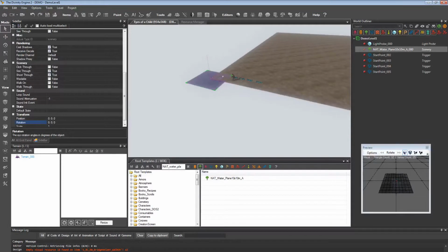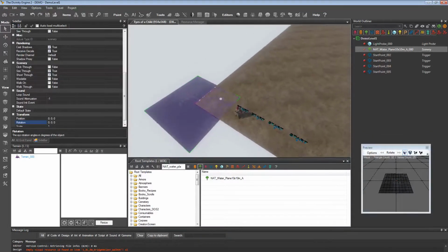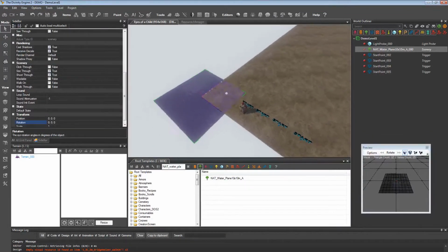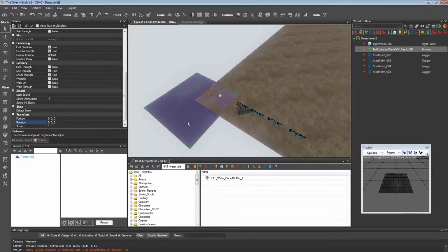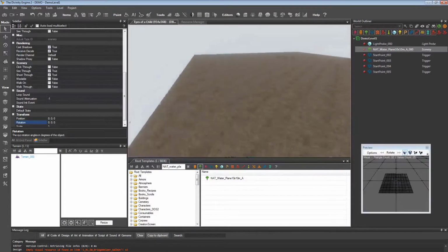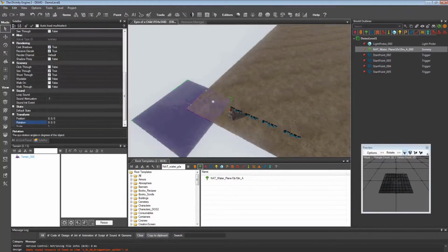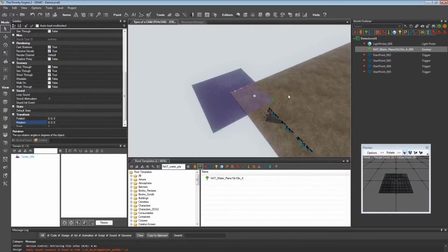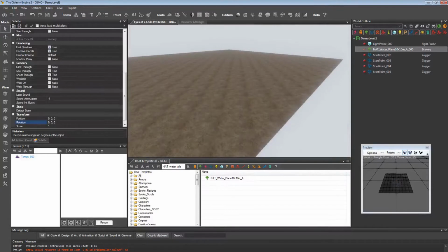And there we have it. They're misaligned, but that is normal because the terrain position is indicated by its corner, and for the scenery, position is indicated by the center. So we're going to have to offset it in order to center it correctly, but we also want to scale it because right now it's too small to cover the whole terrain.